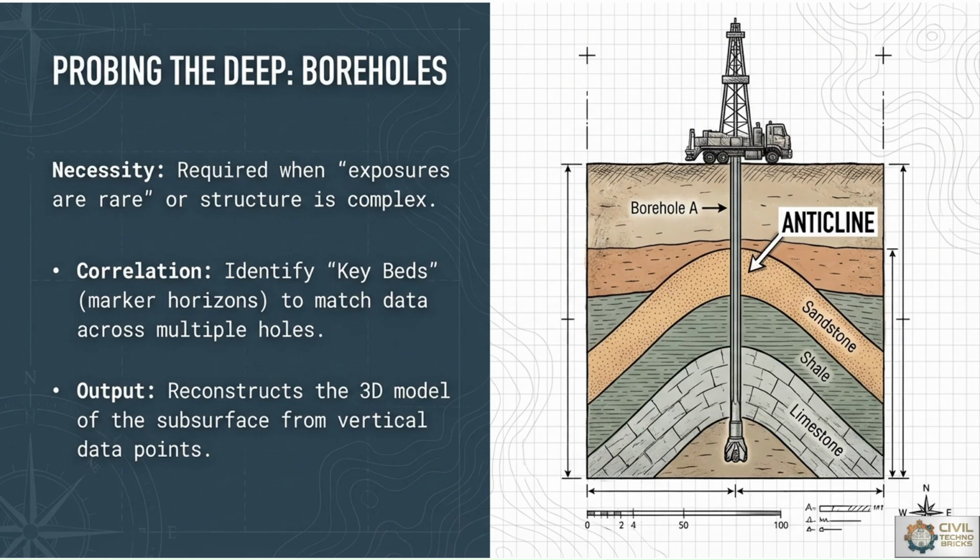Boreholes provide detailed information regarding underground strata, groundwater conditions and rock quality. When we go deeper in the investigation, engineers use drilling techniques to create boreholes. Different drilling methods such as auger boring, percussion drilling, and rotary drilling are selected depending on the ground conditions.